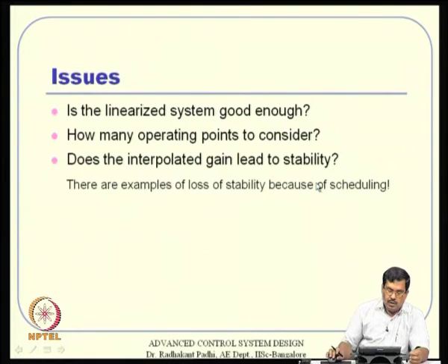Okay. So, does the interpolated gain lead to stability? Need not be. Okay. And there are clear examples of loss of stability because of scheduling, where the individual gains were good, but once you schedule them, it loses stability. So, that is a major concern because of which we need to do several runs of simulation, different randomized simulation, what is popularly called Monte Carlo simulation. We need to do a lot of simulation like that to have confidence in the design basically, and that may or may not be necessary in the nonlinear control design technique.